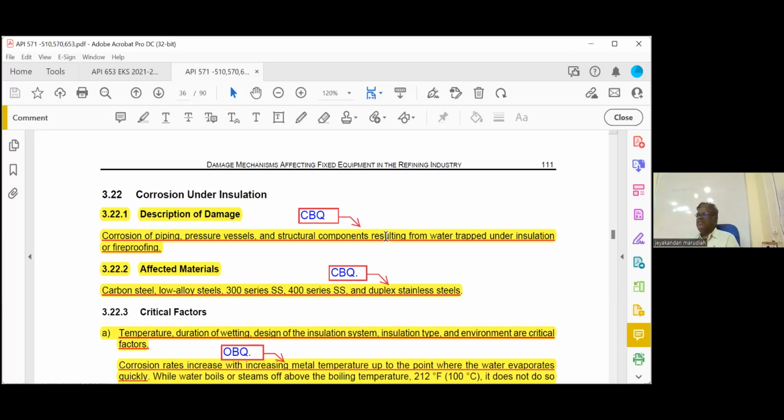How will you maintain a barrier? Use an aluminum spray paint on carbon steel tanks before insulation. Why are they using aluminum spray paint? Because aluminum will corrode preferentially over steel, by what is called galvanic corrosion.